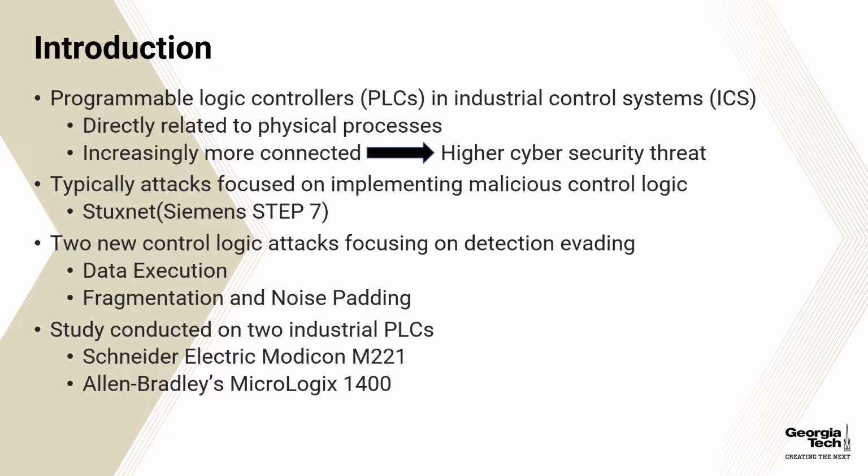Stuxnet became the gold standard of examples for remote attacks on ICSs. In this attack, a nuclear facility in Iran was remotely targeted via their Siemens S7-300 PLC. This attack was meant to sabotage operations and consisted of malicious code which was injected, causing oscillations in centrifuge motor speeds until system failure occurred. Since this attack came to light in 2010, more and more ICS bugs have been reported, and that number has increased almost exponentially year over year.